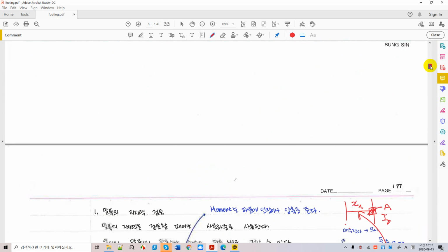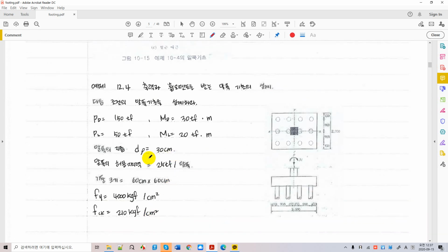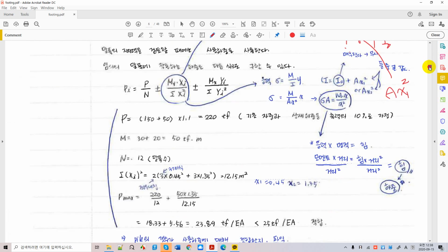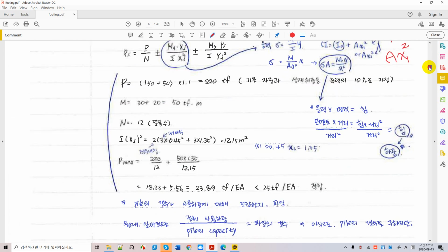Because you are going to have at least this right here. Okay, where is it here? Here you go. 25 tons per pile, 250 kilonewtons. So this pile capacity should be ensured. You have to make sure that your construction possesses this pile capacity. Why? All your pile foundations, including deep piles, pile caps and rebars, everything is based on this very important parameter, which is 25. That number is the allowable pile capacity per pile.